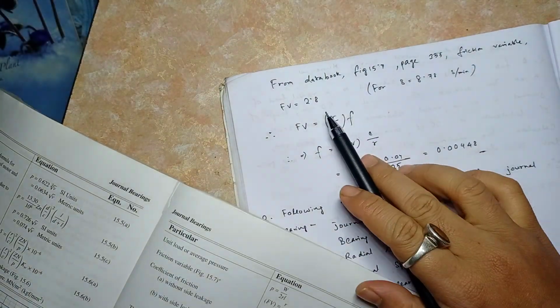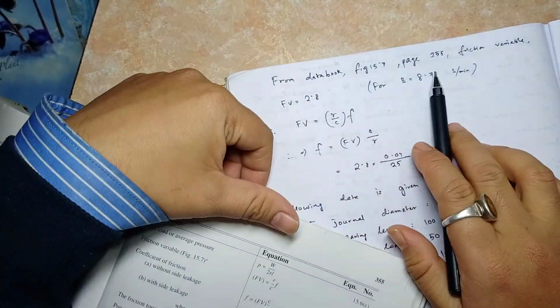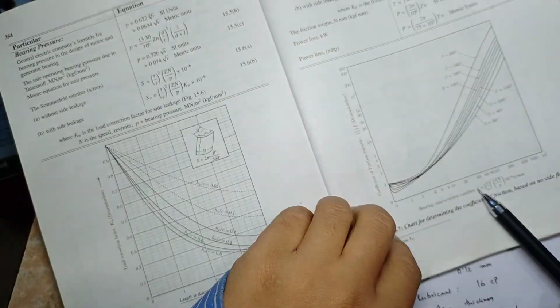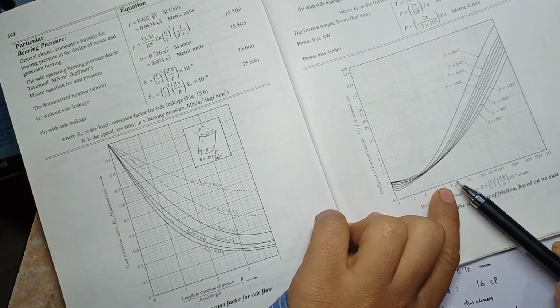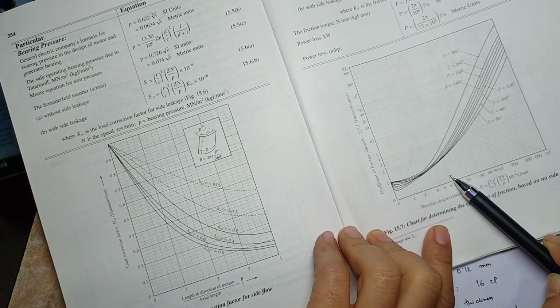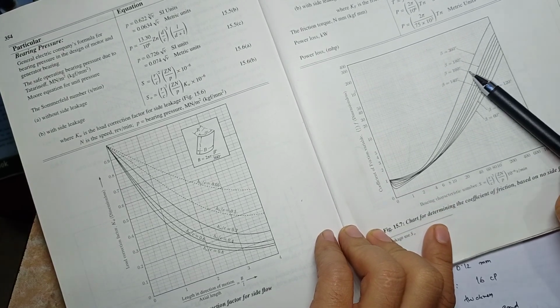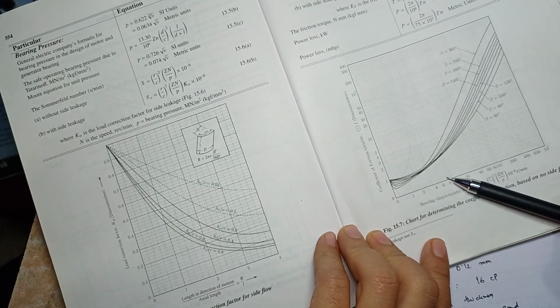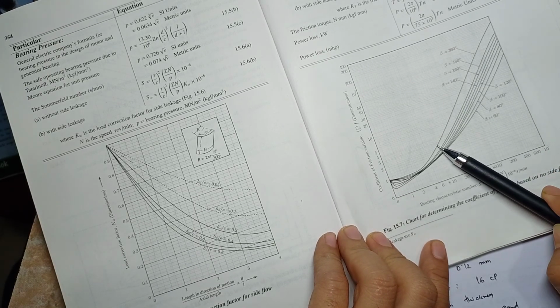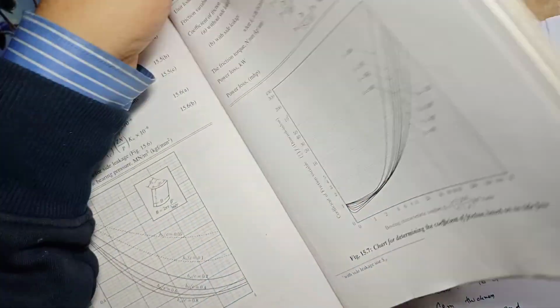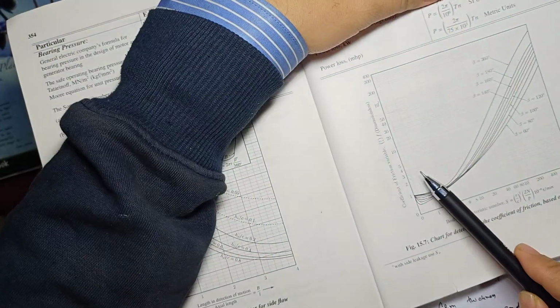So this is the friction variable that we need to get from this figure. The bearing characteristic number is now 8.7 something, so it will lie here somewhere. This is the line for beta 360 degrees. Here it will make an intercept, and this is the value. So we can take the value as around 2.8, very near to 3.